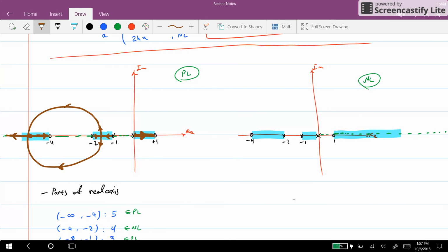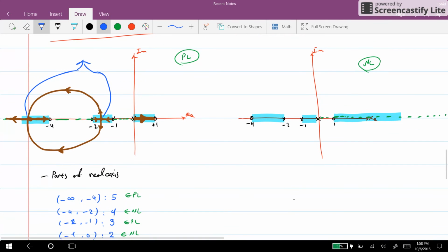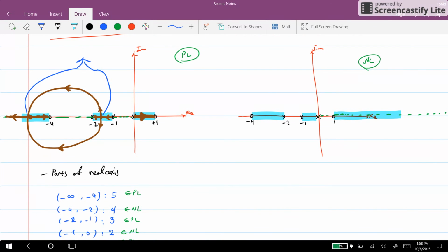for the positive locus. But again, keep in mind that these two points, the break-in and breakaway points, are not known for us. They are the roots of m prime d minus d prime n, but for now we can just think that they are somewhere over there. They are not very important here because they don't affect the stability of our system. But if you want to have the exact root locus plot for this system, we need to find the break-in and breakaway points.